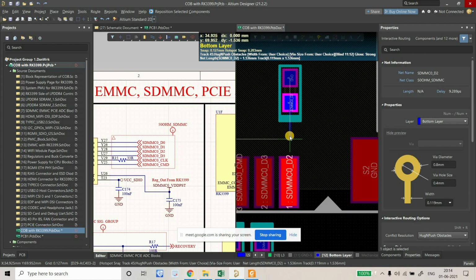See, what people basically do, they just place these ESD diodes behind the connector, right? So what is the purpose of the ESD diode? Whenever there is electrostatic discharge through the connector, it will first go to the ESD diode, and all the electrostatic discharge will pass through the ESD diode rather than traveling throughout all the connections. Otherwise it will create a lot of issues, and it can create a huge fault as well, right?